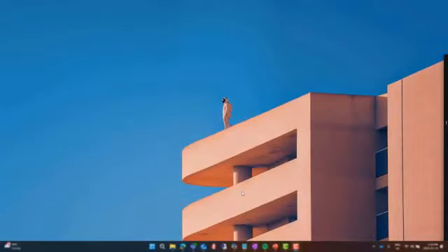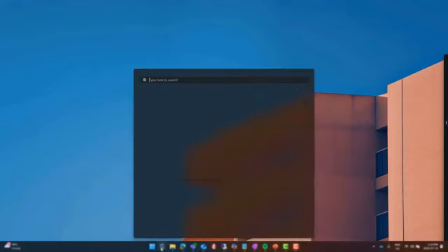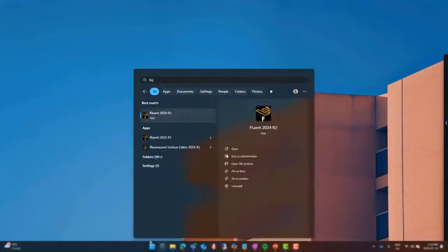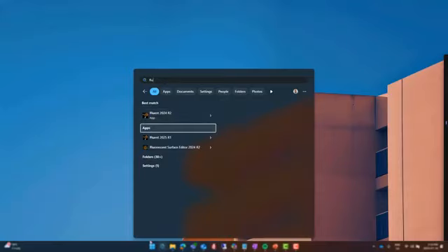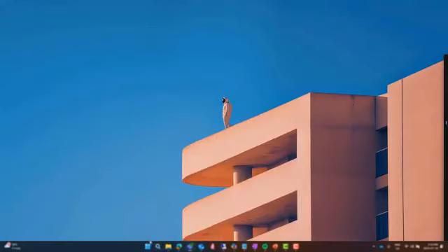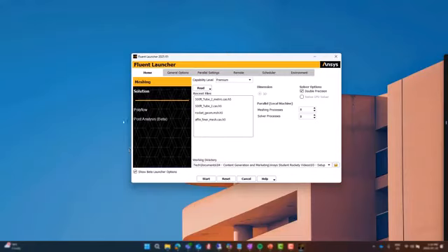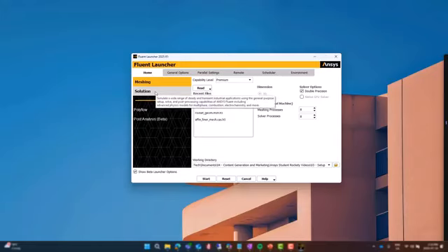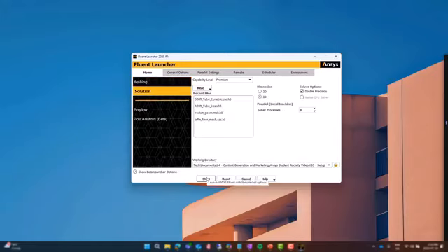If you've already been provided a prep geometry and mesh, or you're wishing to continue working on an existing case setup, you can launch Fluent from your Windows taskbar. For this simulation, we're using version 25R1. And when the launcher window shows up, ensure you're launching your simulation in the correct working directory. You select the number of processors that are relevant to the machine you're using. Double precision is selected, as well as the solution launcher is selected. And start.